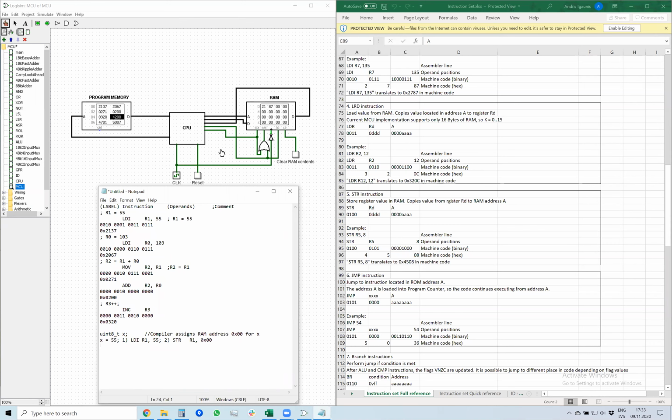Intel processors, desktop machine processors, of course, could do it because they are more expensive. They cost 300, 500 euros. So yes, they can do it so that the processor works faster. But microcontrollers that cost something like 2 euros or maybe 50 cents, of course, don't have that many wires inside. So in microcontrollers, you can only load a number into a register and then store the register contents into the random access memory location where your variable is reserved. So this is actually how it happens.